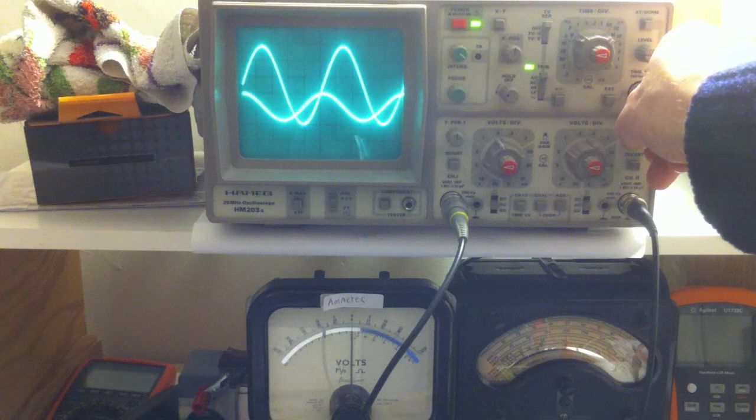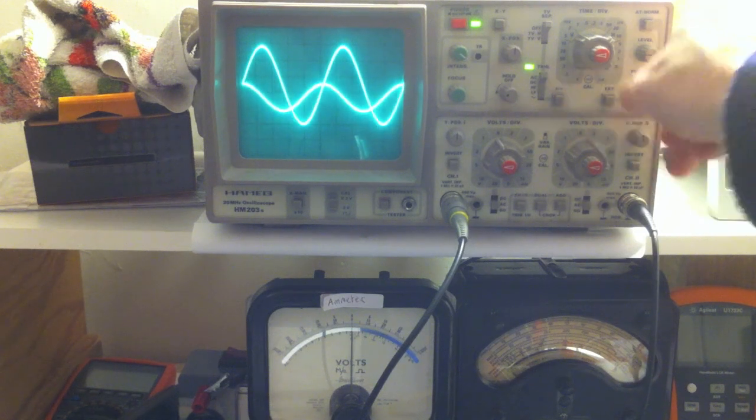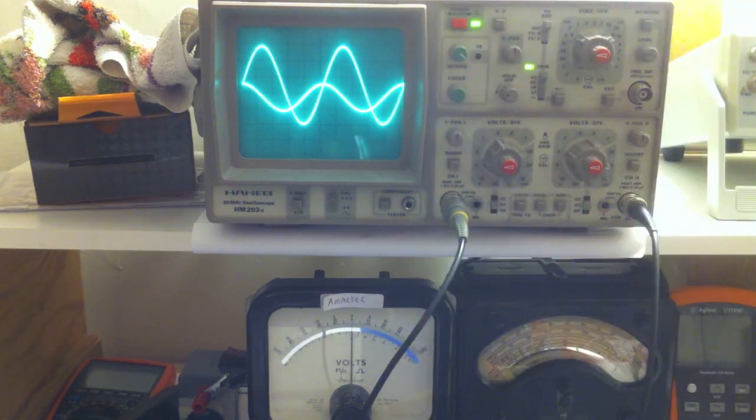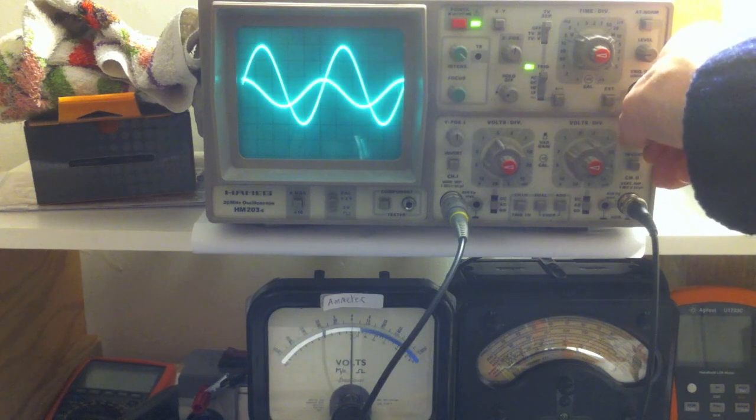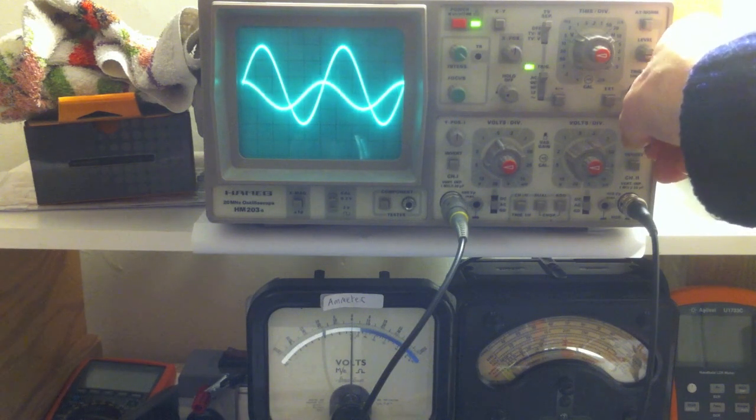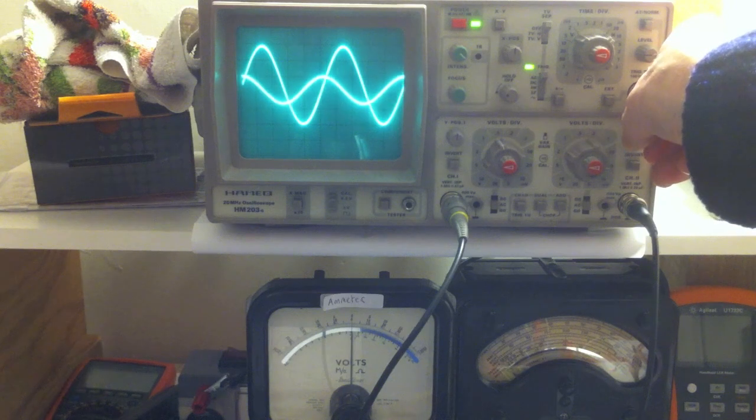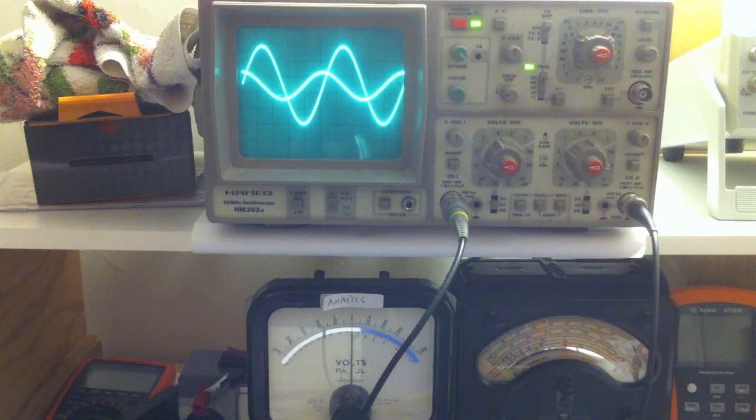You have got a differentiator there, and the reason it works is because of the way that the capacitor is charging and the voltage is dropping across the capacitor. Any voltage that drops across the capacitor is not dropping across the resistor, and vice versa. So although it might sound very complicated when you hear the word differentiator, in essence all it is, is a sharing of voltage between the resistor and the capacitor.